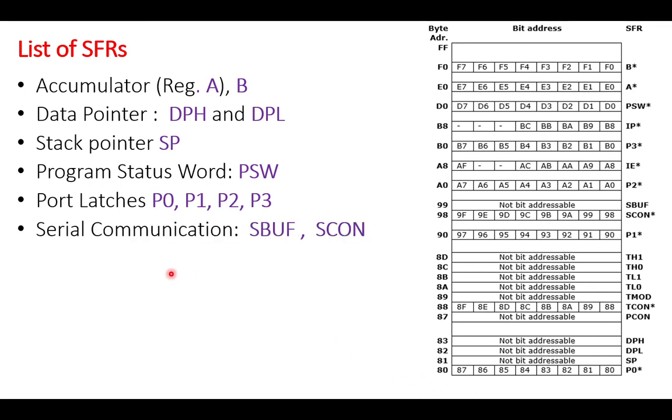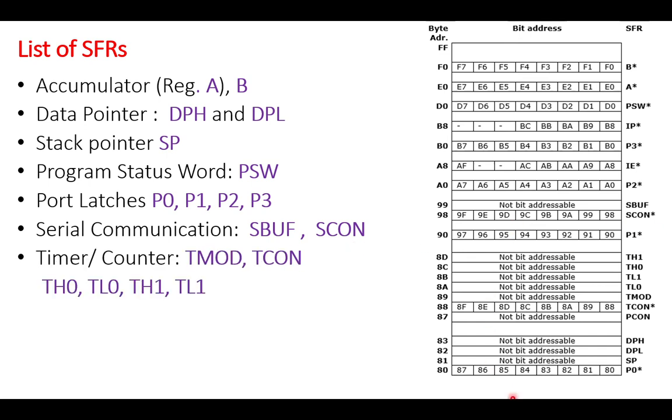8051 has the facility of serial communication, and there are two special function registers related to serial communication. They are named SBUF and SCON. Out of these two, SBUF is not bit addressable and SCON register is bit addressable.